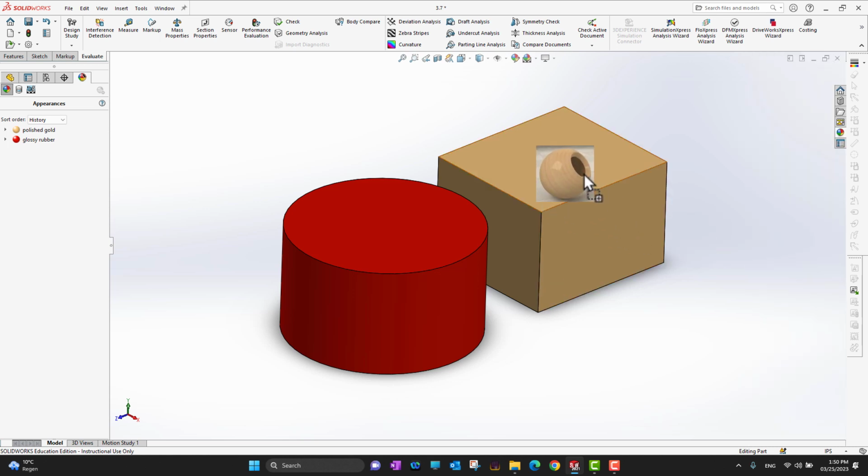Suppose I want to have the texture or finishing of wood, again for the whole body. Look at that. In this way I can change the texture or finishing of my part into a wooden finishing. No matter what material you have, and again I'm repeating this, keep in mind it's not gonna change the mass properties, it's only gonna change the texture, appearance or finish.